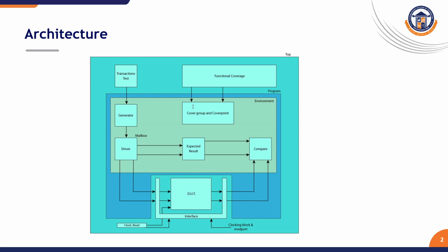Since the data paths for both the DUT and the reference model will be different, the output receiving time for the data could be different too. Hence, the data needs to be stored. Synchronization needs to be set between the expected output and the actual output. Once everything is synced, both outputs can be compared to figure out whether any defect exists.